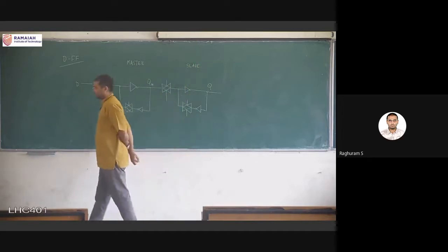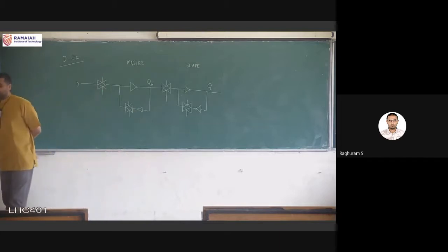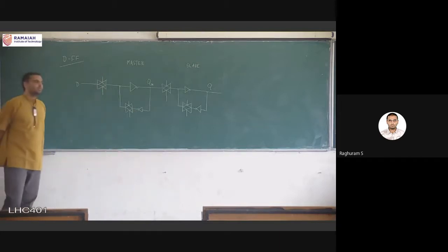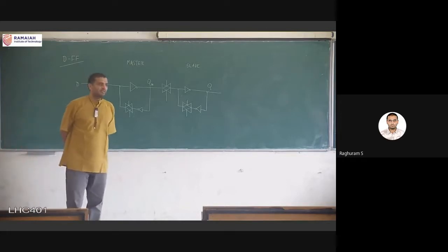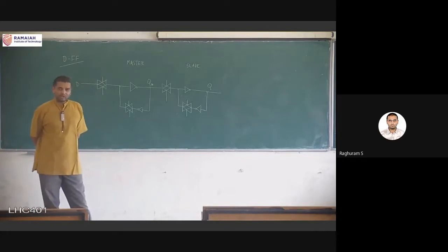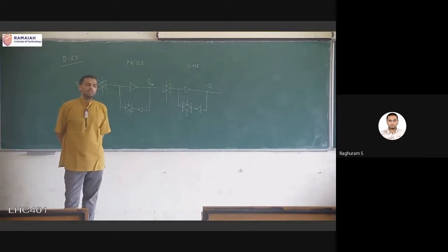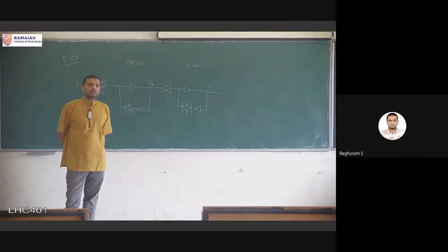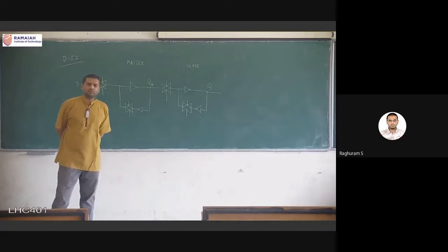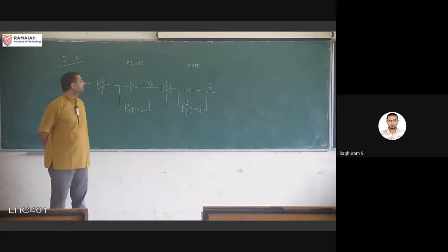Okay, so instead of, this is again one of the principles of regularity, instead of starting from scratch and designing a completely new circuit, if we have a good circuit with proven functionality for a latch, we will try to reuse that and get a flip-flop, and one of the results of that requirement is this circuit. So there are other ways also. This is not the only way in which we can make an edge triggered flip-flop.